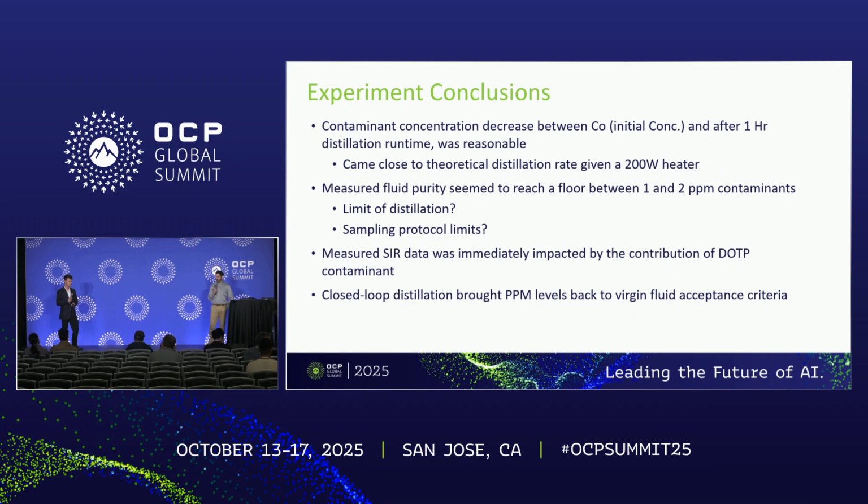We also observed that the SIR measurements responded immediately to the addition of the contaminants in the tank, and they only partially responded to the cleaning of the fluid. So it is possible that it requires a longer exposure to the clean fluid in the tank to disperse the residues and recover the resistance data, or it's possible some other cleaning protocol may be required.